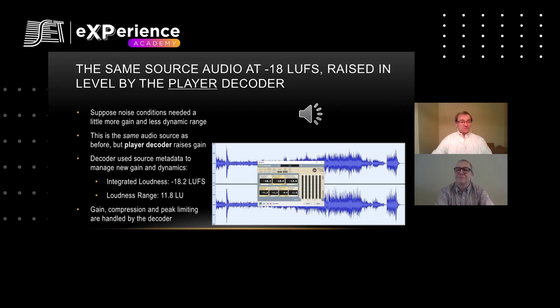Okay, so that was clearly louder in my earbuds right here. I didn't touch the volume control. Now you might be asking yourself, well, what's the difference between this and just turning up the volume control on my player? Well, it has some of the same effect, but we started with the same source material and we reduced the dynamic range to make it more satisfactory in a noisier environment. And that's the difference. The dynamic range was changed. We didn't just turn all of the music up together.